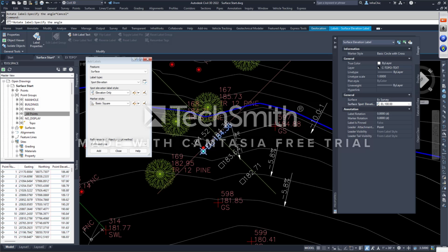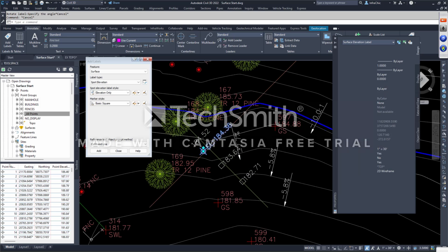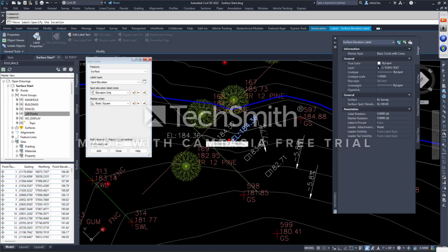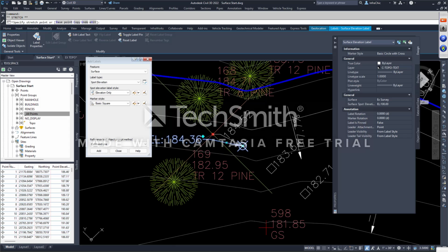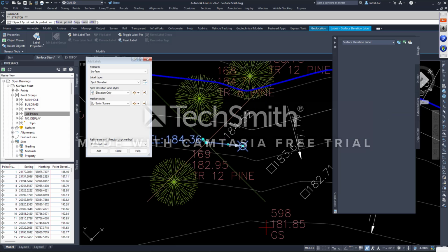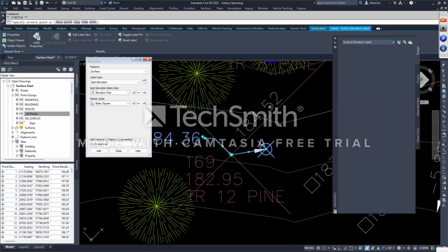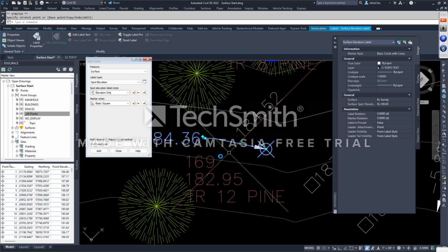If I grab the diamond, let me try that again. Escape twice. Once. Hold on. Grab the diamond. Now I'm going to go into what's called a dragged state. When you go into a dragged state, the leader portion of the label style is activated. You get an arrow. You get the ability to maneuver the label wherever. The square closest to the label will change the leader location where it marries. When you change something up by the leader, you get a square to go back. You can add another bend point on your leader. And when you change again, you get a square to return home.